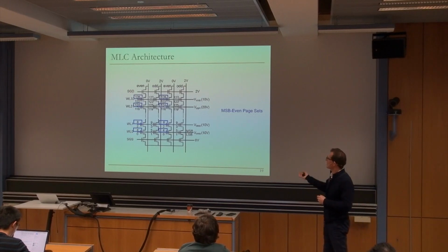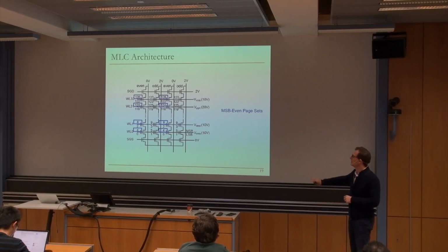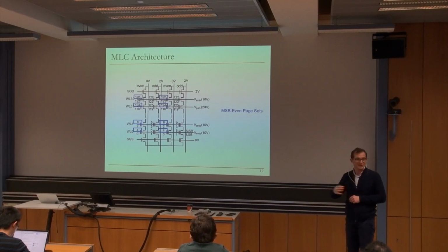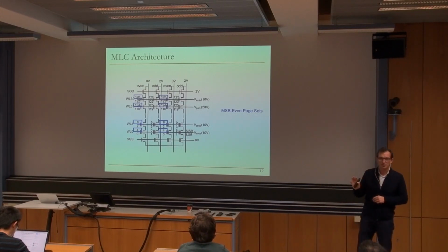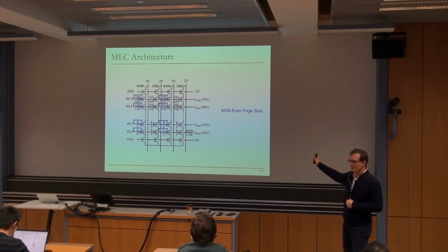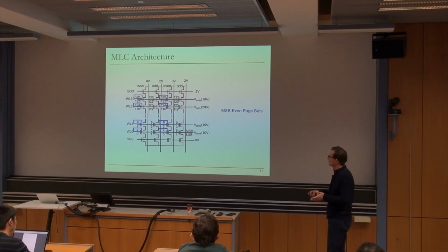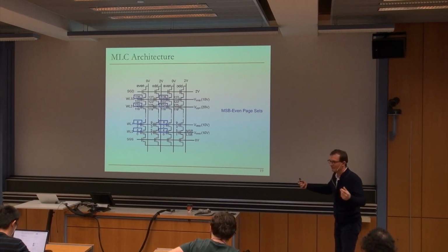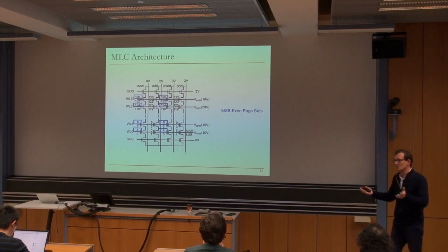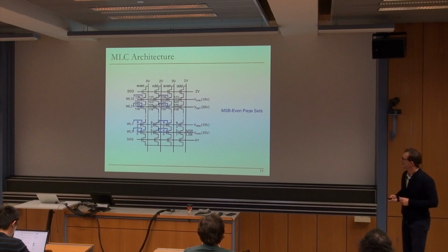And the way people usually program pages after they erase a block, they want to minimize that interference. And there are algorithms that are developed to minimize that interference. I'll point you to a paper that talks about that. It's interesting, but basically you want to minimize the interference such that you don't destroy the values in the pages that are next to you. That's the idea. So that's called write disturb essentially, or program interference.